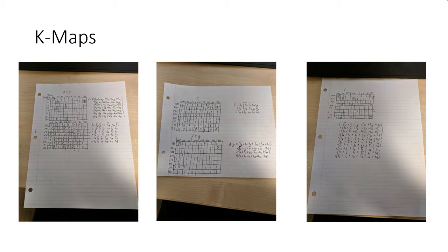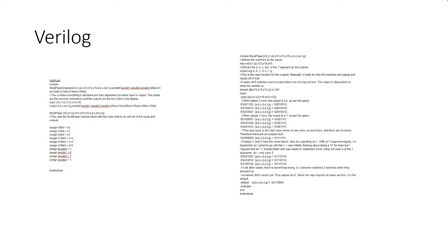Something else that's interesting to notice is how massive these equations are. That is because the K-maps themselves are massive. They're 6 variable, which means they're 8 by 8. They're just really big, and you see how each of the circled things is not next to any other circled thing. That means I wasn't able to minimize the equations, which means the equations ended up being fairly large.